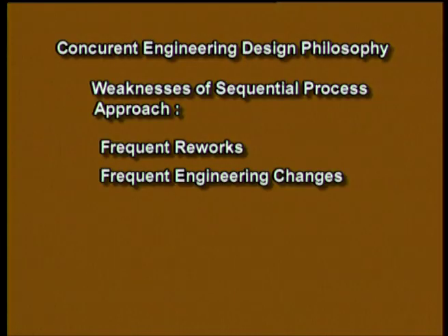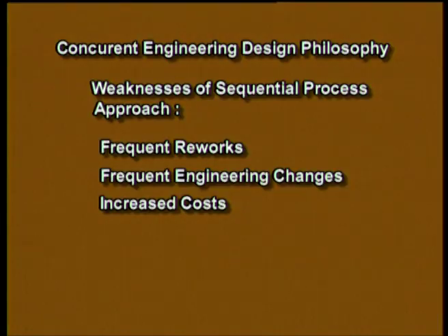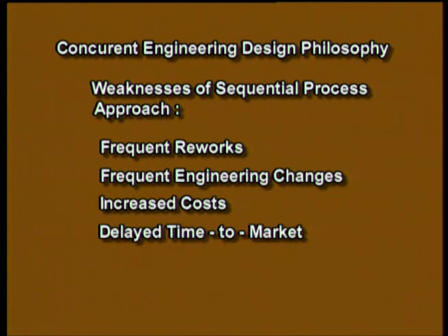So that is what the sequential approach promotes, and as a result the disadvantages are frequent reworks back and forth, and also major engineering changes quite frequently. At the manufacturing stage, the product goes back to the design stage, and then all the frequent engineering changes take place consequently, with increased costs and delayed time to market.